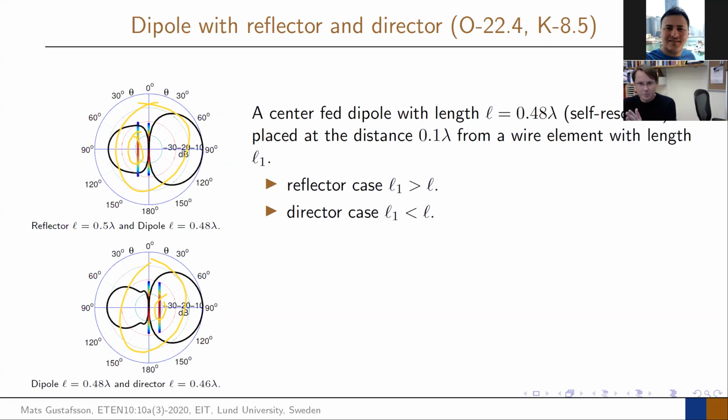If you think the dipole is just crossing through, the reactance is 0. If you then change the length, you move a little bit to the left or the right of that, and you make it either inductive or capacitive. And that's a change of the phase of this induced current. By playing with this length, we can get the radiation going in the direction where we would like it to go.